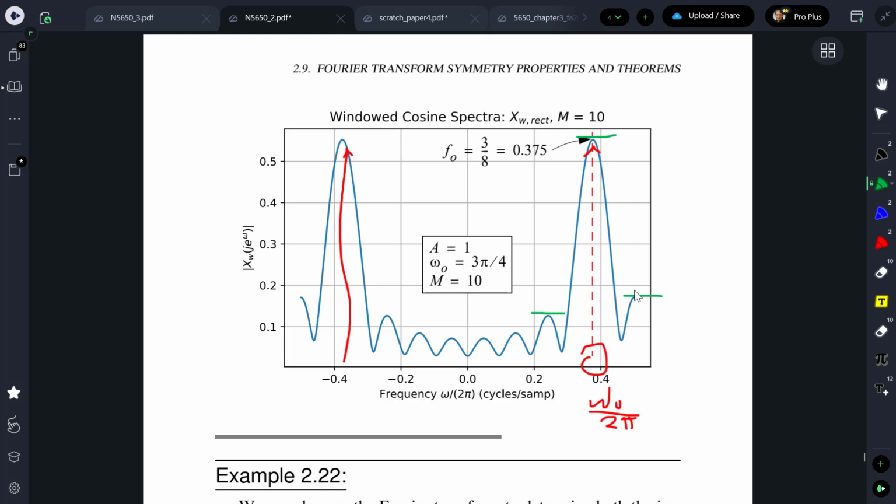And if there was another signal here that was close to the frequency of the signal that we put in, the bigger signal, it would produce a superposition. It would superimpose another one of these blobby things, but it would be hidden down over in here, and washed over by the side lobes from the stronger signal. That's called leakage. The primary signal is leaking energy out in the frequency domain to the other bands, and then it can mask over a weak signal. In military operations terms, or even for vehicles on the highway with a radar system tracking whether there is a car in front or behind, a small object like a motorcycle will have a smaller radar cross-section and less return, and it might get lost in that clutter or that leakage.